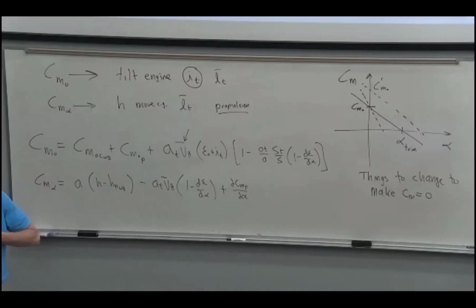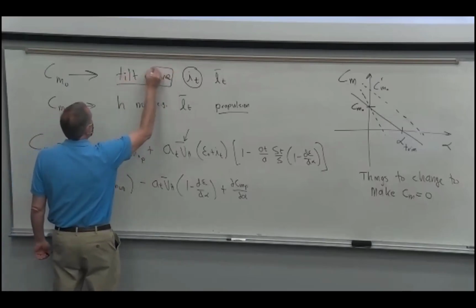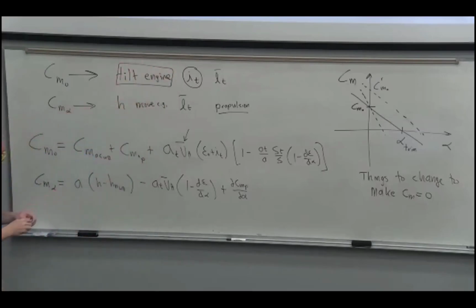Structurally, it's harder to do because then you've got to have some kind of a hinge or a pivot point that carries the whole load of the tail through that and still allows it to move to the airplane. So that is an option. Tilting the engine is an option. But then structurally, you've got to have that engine mount made so that it can tilt the engine. Right? We do that with vertical takeoff and landing and some other airplanes.